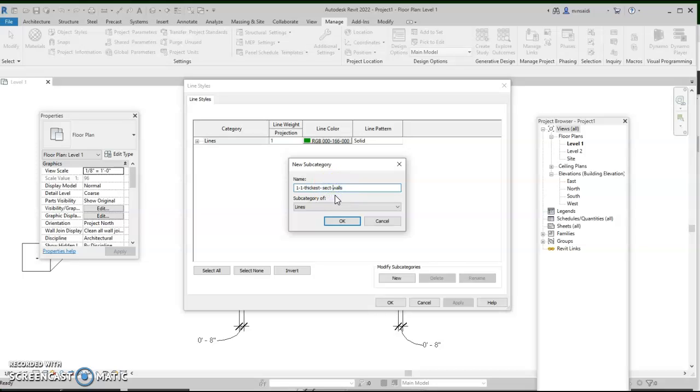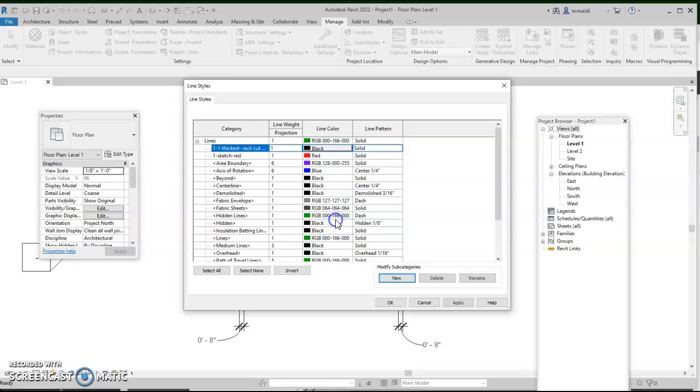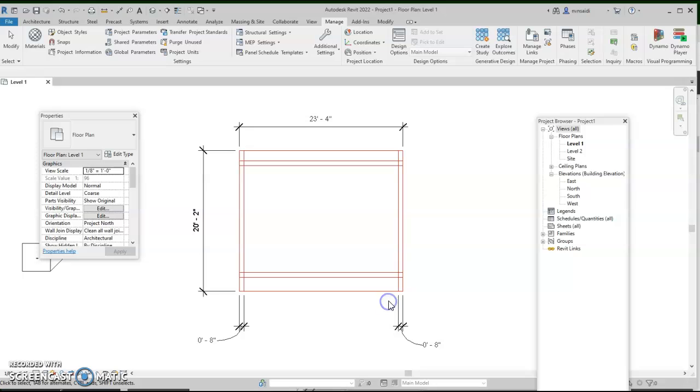And I'm going to do cut, so it reminds me what I'm going to do. And I would like it to be black, but the line hierarchy, I like it to go thick. So I'm going to choose either 6 or 7. Let's choose 7. And you will be more articulate with your line number later on. Right now I'm going to choose 7, and I say OK.